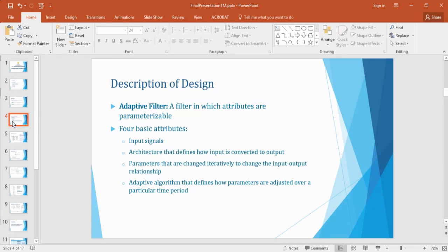So now let's look at two types of filters, which are fixed and adaptive filters. A fixed filter is something that requires a prior knowledge of signals and noise ratios. So it is possible to design this filter so that it passes frequencies contained in the signal but rejects the frequency band occupied by the noise. The next thing that we are basically trying to design here is an adaptive filter.